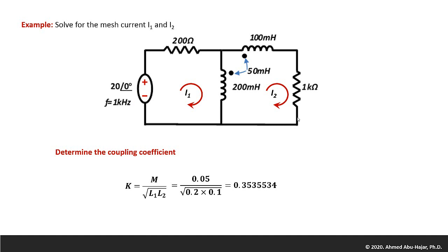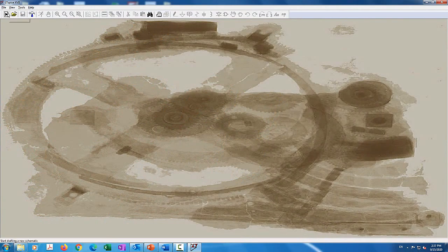So I'm going to start loading LTSPICE now. I click on Start LTSPICE. I will create a new schematic. I'm going to start with the inductors first and define the mutual coupling between them. So I'm going to place this inductor L1 here, and as you can see, L1 doesn't have the dot defined here. So what I'm going to do is come on the top of the inductor.